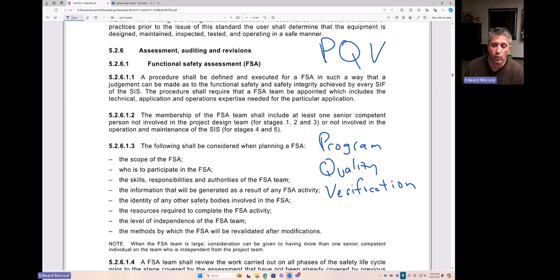One of the requirements would be, for instance, if we go to clause 11, there's a requirement that says when a shutdown occurs, there should be a manual reset unless the SRS specifies otherwise. That is the requirement. Now, for you as a company, you need to have a program that makes sure that requirement is implemented consistently.